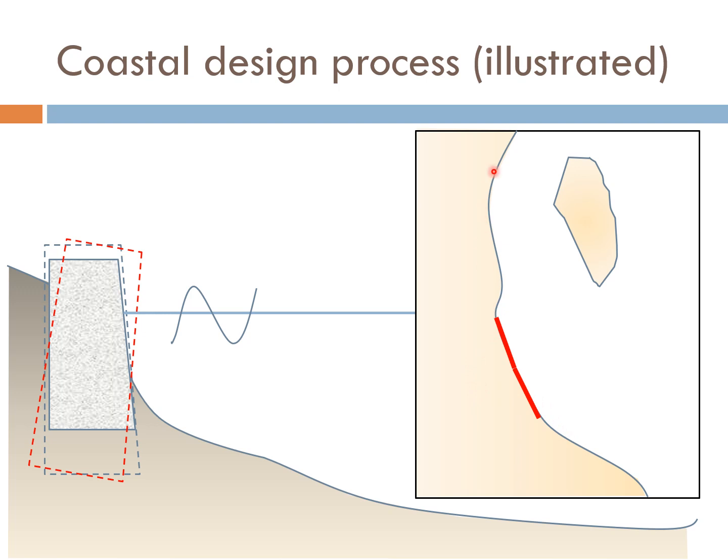Now, we also would like to know what is the profile of the beaches along this stretch of shoreline, what is the bathymetry, and also the sediment material in this area. We can use satellite images to find out whether there's any change of this shoreline historically, whether there's any sandbar formation, any shoreline retreat or erosion, for example, and also to find out what the coastal littoral process is like, whether there is a net loss or net accretion. So all this information is vital.